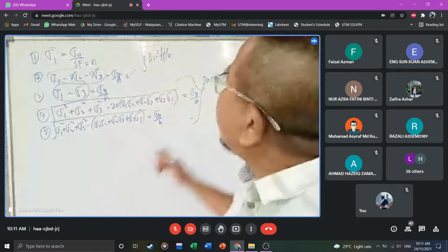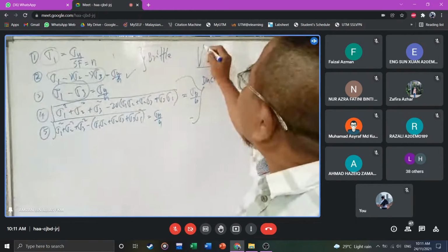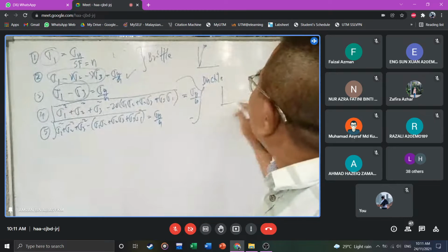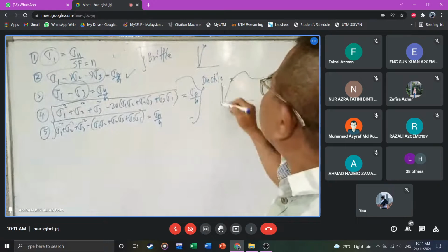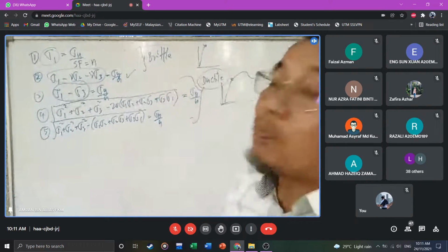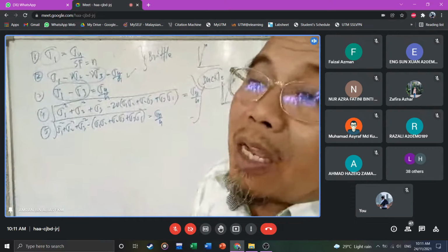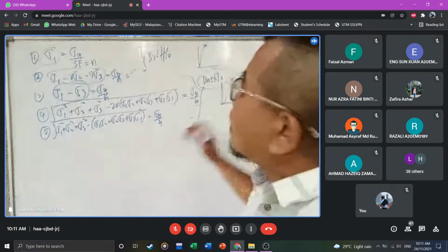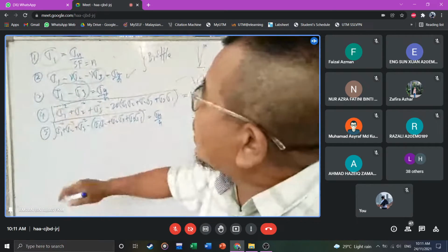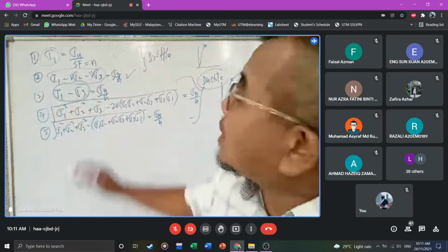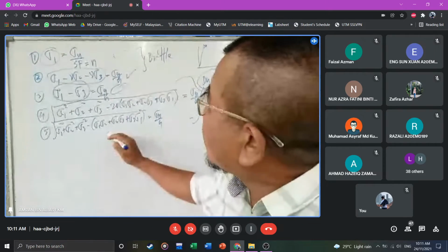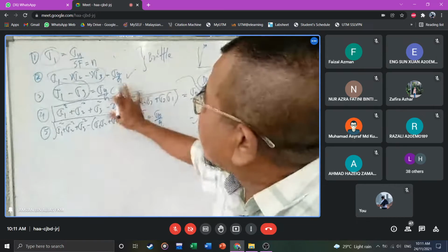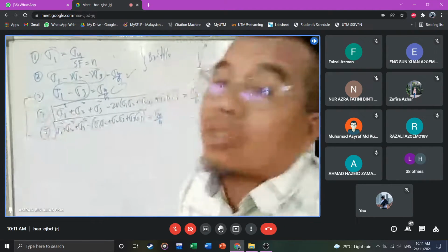What's the meaning of ductile? That one is brittle, brick. Ductile, here we have a lot of plastic area. So ductile materials, most metals, steel, aluminum, copper, are all ductile. So the last three theories, the most famous and easiest one is Tresca. And the last one here is von Mises. So these two theories here are the most used.